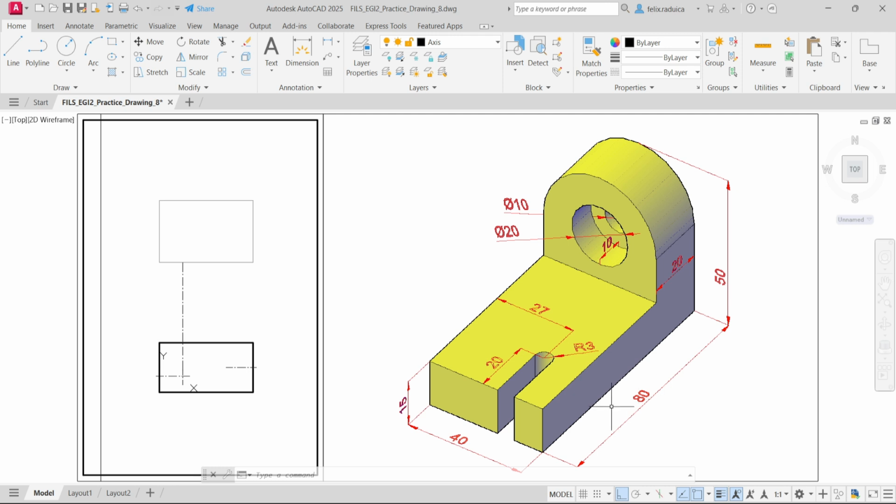Now all I need is an axis, which is, this is 15. So I need 15 and also 3 towards the top. So line again from here and tap 18. Tap enter twice, select this one and delete it. I no longer need it. And then I want this to be 3 millimeters longer on the bottom part here. So I have this axis line, which is in correspondence with this one.